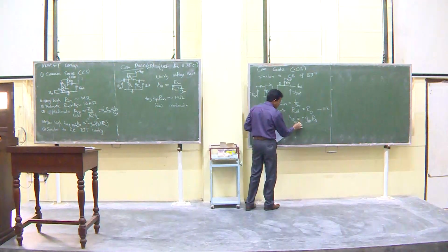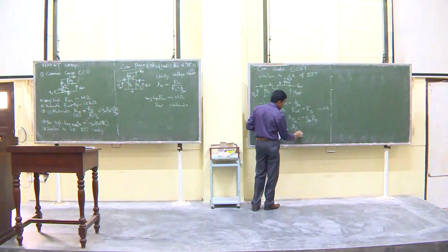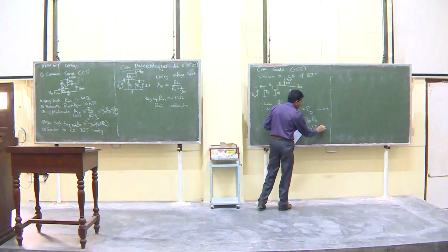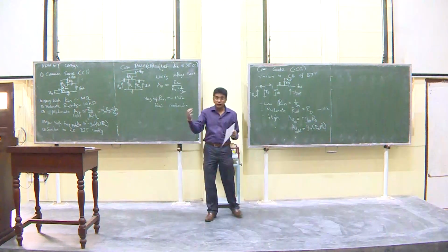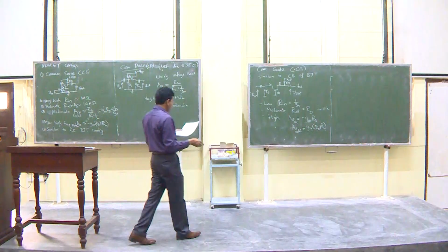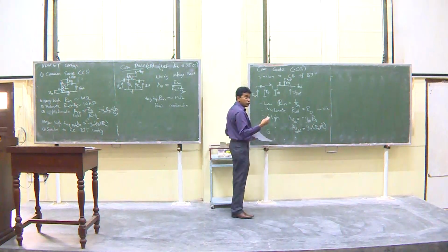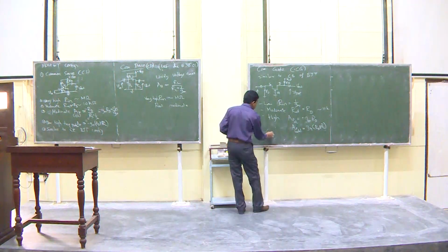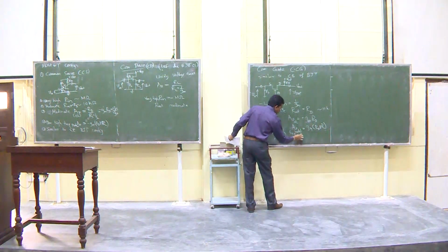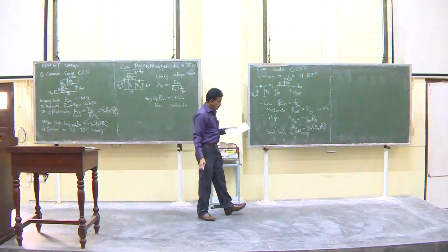This is the open circuit. When you load it, it becomes loaded. This becomes GM times RD parallel RL. You don't have to memorize any of this, we will be deriving them, okay? Don't try to memorize this, but just to give you an idea about the values, okay? Good high frequency response, so this is better for high frequencies. Good high frequency response, and similar to the common base amplifier.